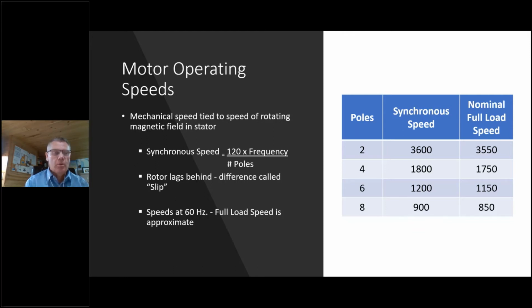We're talking about small percentages of speed differential. And if you see larger slips or larger nominal speeds or asynchronous speed, that could often be an indication of a higher torque motor. In this simple calculation, the way we arrive at those speeds is a constant of 120 times the frequency, whether it's 50 hertz or 60 hertz, by the number of magnetic poles. And that's how we know.